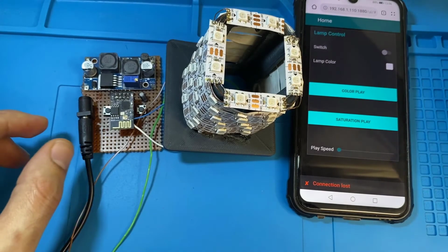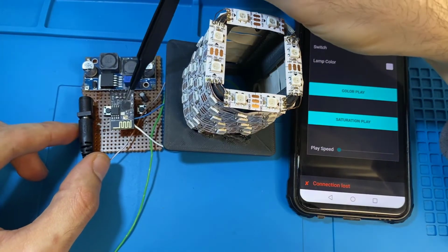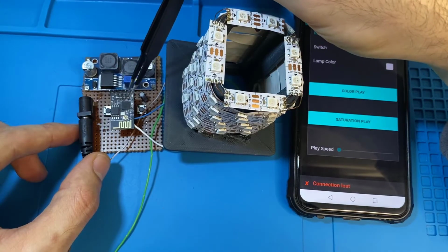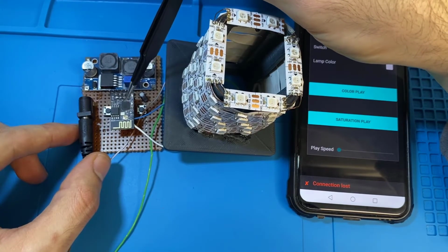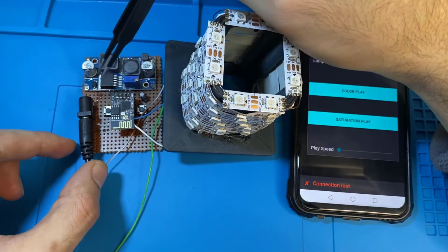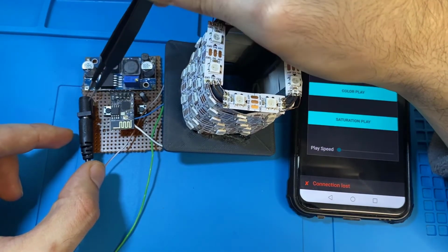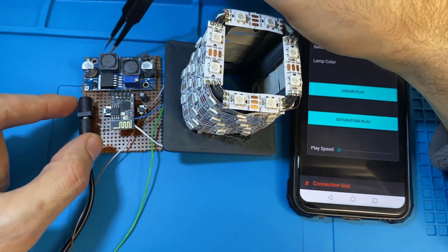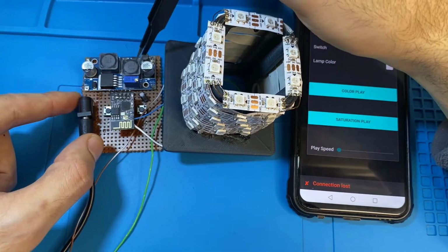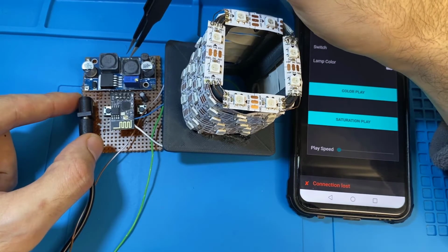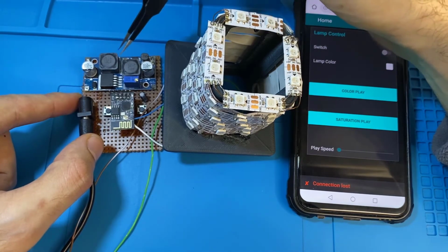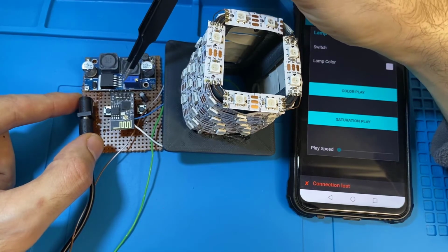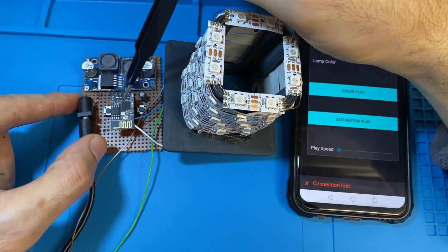Alright, so here's my setup. Let's start explaining with this board. Here I'm having the ESP32C3. This module is quite similar to the one that has the ESP8266. It's manufactured by Lilygo. And this board gets its power from this jack connector, which is supplying 12 volt. And here I'm having a buck converter that reduces the DC voltage from 12 volt to 5 volt. And at the back I'm having an LDO, a linear voltage regulator, that's dropping that voltage from 5 volt to 3.3 volt, so I can power this ESP32C3.